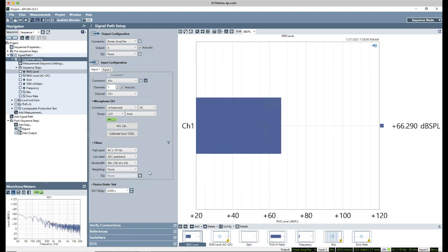Now, I will say that strictly speaking, calibrating from TEDS is a bit of a misnomer. I'm not really calibrating the microphone. I'm reading the previously stored calibration data out of the microphone and using it. So, you know, if I was being very, very thorough, I might separately attach an acoustic calibrator to the microphone to verify that the calibration hasn't changed since the last time I've used it. But this is a microphone I use fairly frequently, so I'm satisfied with the TEDS data.